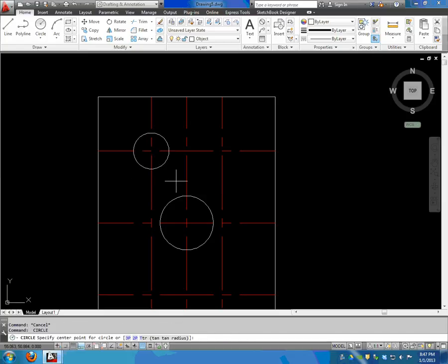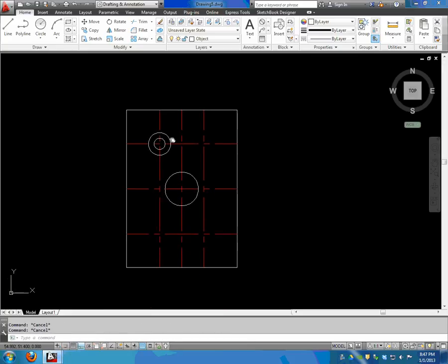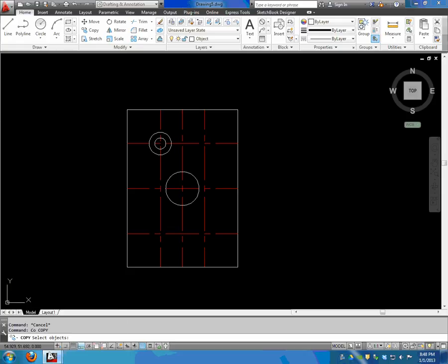That's our diameter. Now we have our depth. We can worry about that when we do our other views. Do our apparent intersection again, and that diameter is 0.25. So right there, that's typical, so we can just copy these views over. Center and intersection. So we have that information now.